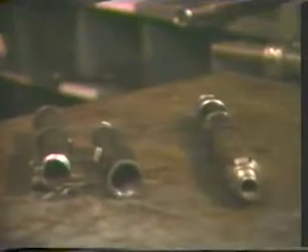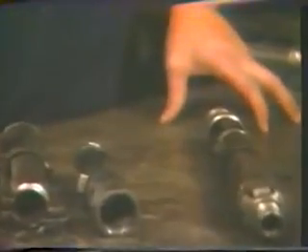Tubing locks are lock mandrels that can be anchored in the tubing without any special receptacle being provided. Slip locks anchor and seal on the ID of the tubing, while collar locks, like collar stops, use the collar recess in API threaded and coupled pipe for anchoring the lock mandrel. The main advantage of the collar lock mandrel is the higher pressure rating for all sizes as compared to the slip lock. This is because the lock uses the collar recess on API threaded and coupled pipe as the locking profile. This provides a more substantial surface to support the lock mandrel. These locks are also capable of supporting a positive pressure differential from both directions.